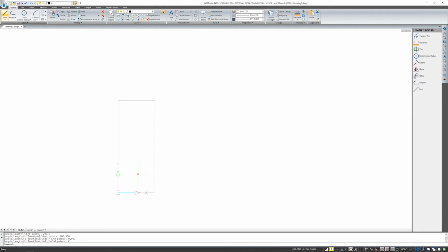If you do not turn off the dynamic entry window when you start drawing from any point, you have to remember that it is relative drawing. And if I draw exactly the same rectangle, before entering the value I have to enter the at sign, and then enter exactly the same first values that were in the introduction of absolute coordinates. Remembering that at this moment, exactly at the place I clicked, the program introduces a temporary point 0, 0 from your coordinate system.